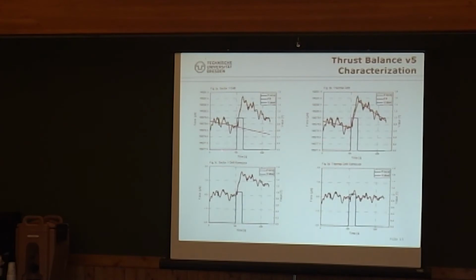So this is what it looks like. I have here sector 1. I fit a line in it, in this part, and I extend it obviously, and then I remove this whole line from the measurement, so I get basically an even thing, and this looks different. And the other method is I have here again my fit for the last sector, and then I connect these two points with a straight line and remove it, and basically I can remove thermal drift.